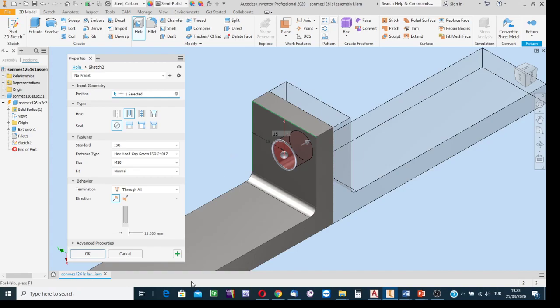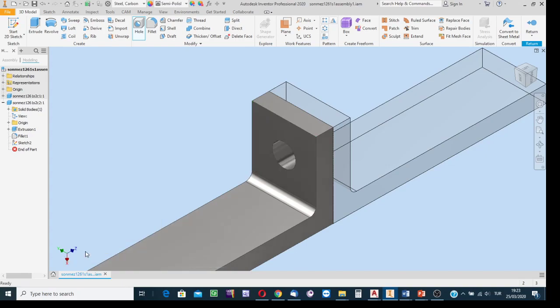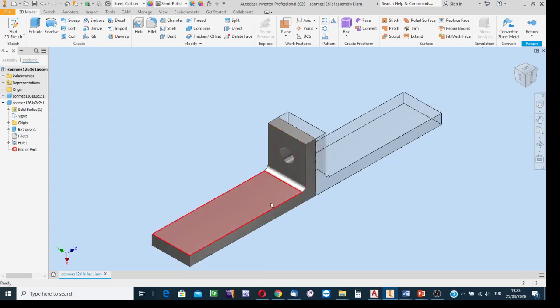Okay, and then click on OK button. Since there is no more hole to create, instead of clicking on add and continue button, click on OK button. Yes, created the necessary hole within this part of the first component. Okay, after finishing the things in edit mode, to finish the editing stage, don't forget, this is important, along the 3D model ribbon, find the last panel.